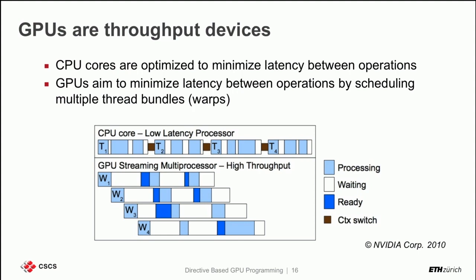And the other thing for the GPUs, if you notice, is that there's no little black box here. So when you switch from thread bundle to thread bundle, you don't have any context switch. We'll see how this can be achieved. That's extremely efficient because, like we said, you have 3,500 cores there, and you can have 3,500 threads.